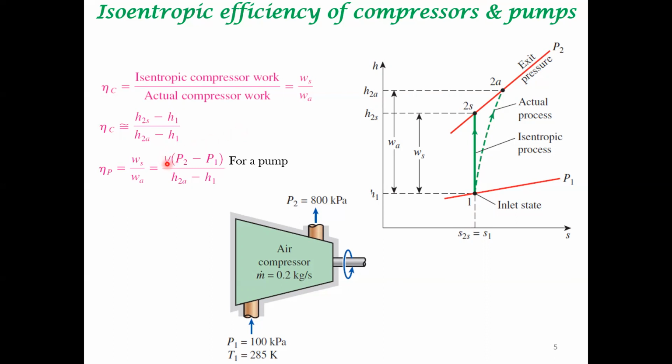The specific volume is not changing. Therefore, we saw this in the previous lecture too. The actual isentropic compressor work in an actual system is still given by the difference in enthalpy, assuming that the changes in potential energy and kinetic energy can be neglected. So you can equate the actual work to the enthalpy difference, the enthalpy of the inlet stream minus the enthalpy of the outlet stream.